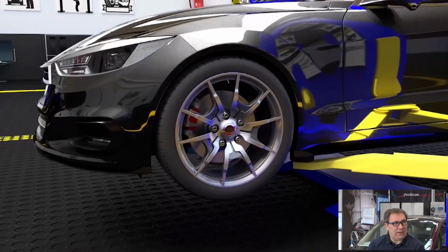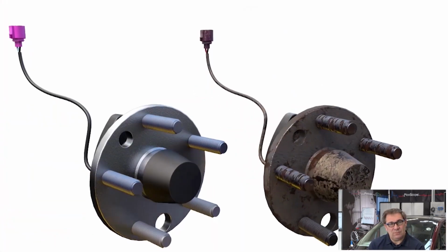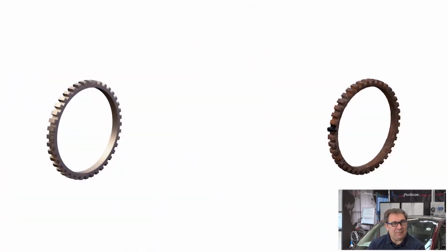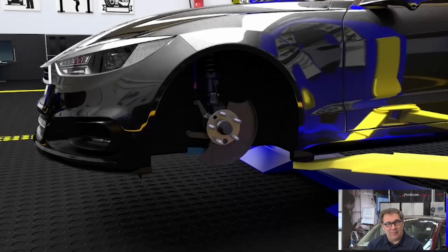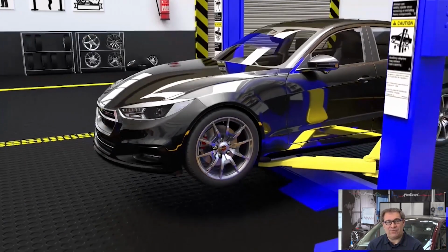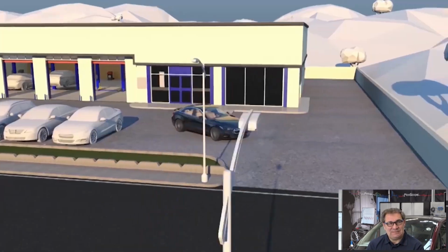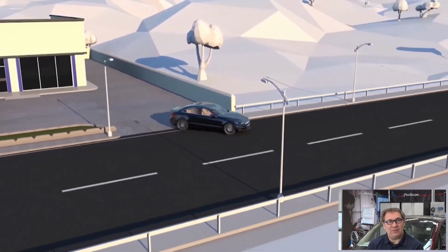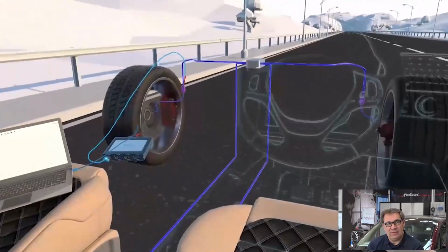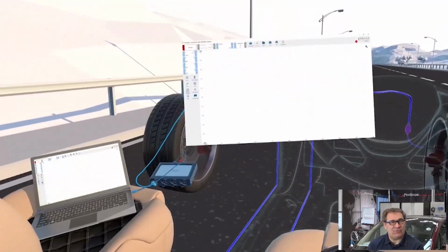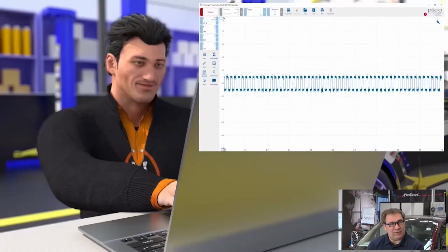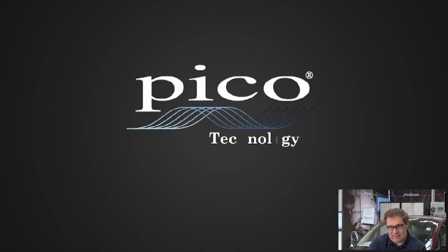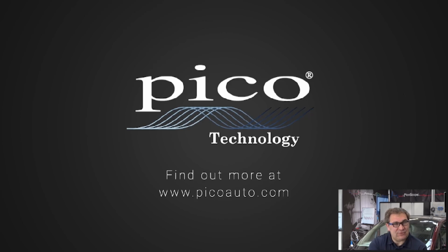So the technician replaces our component and back onto the vehicle. And like we've said a number of times now, final job for any PicoScope technician, retest the component when it's on the vehicle. It's not beyond possibility that you get a faulty component straight out of the box. So there we've got our nice square edge wheel sensor waveform, and we know that the fix is absolutely complete. So that's understanding waveforms.